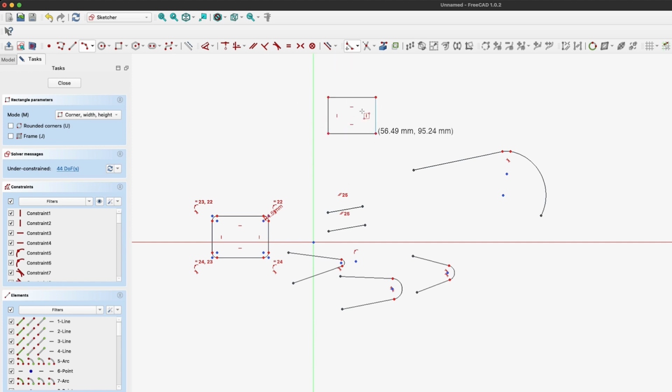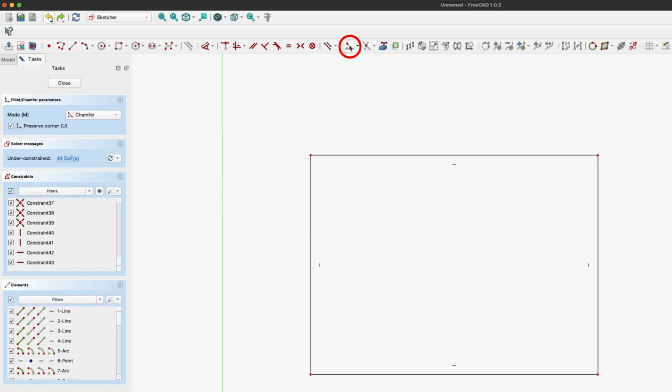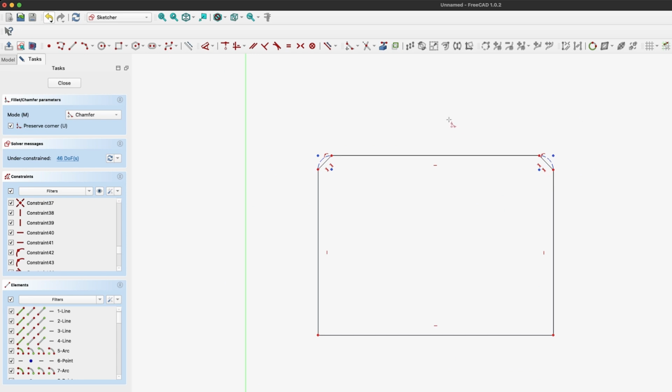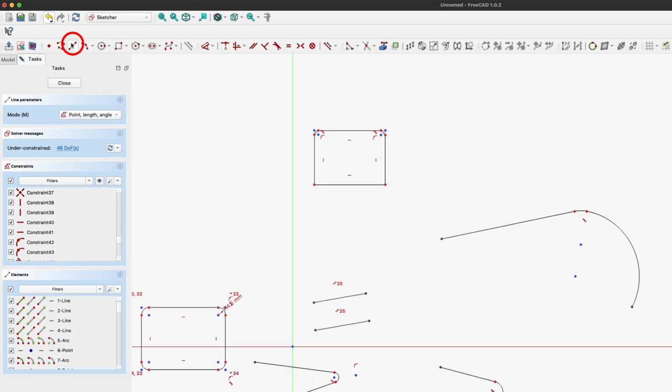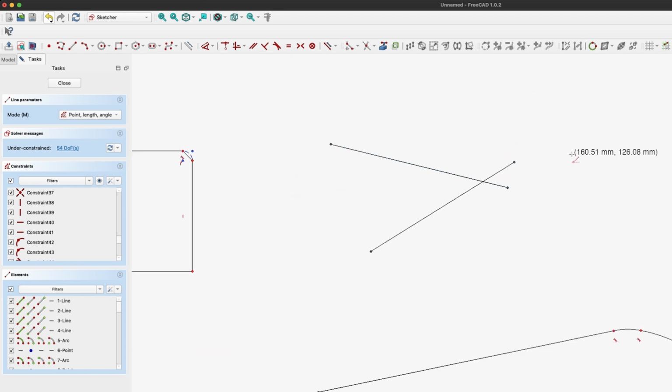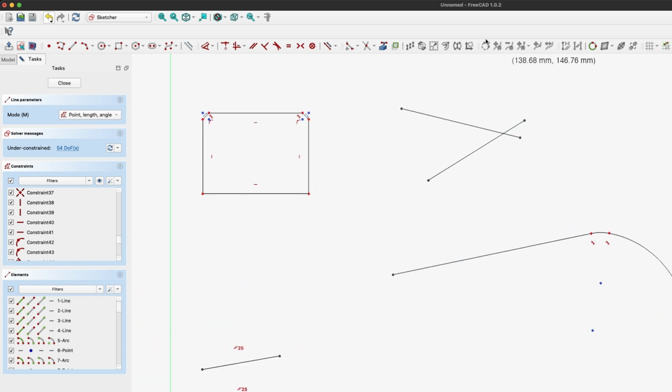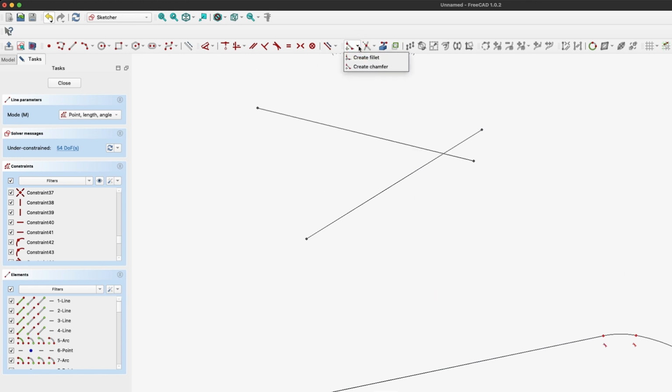Let's again take another example of a similar rectangle, select the chamfer, and there we go, we have added a chamfer. Now in a similar way, if you want to equate those chamfers, you can apply a sizing or dimensional constraint, and then the geometrical constraint, and that's how you're going to apply, let's say, an equal size chamfer all across. Now let me also take another example, and this one is going to be the last in this particular style, because as I said, in both these cases the prerequisite remains the same. That's why both chamfer as well as fillet exist in the same category or same tool.